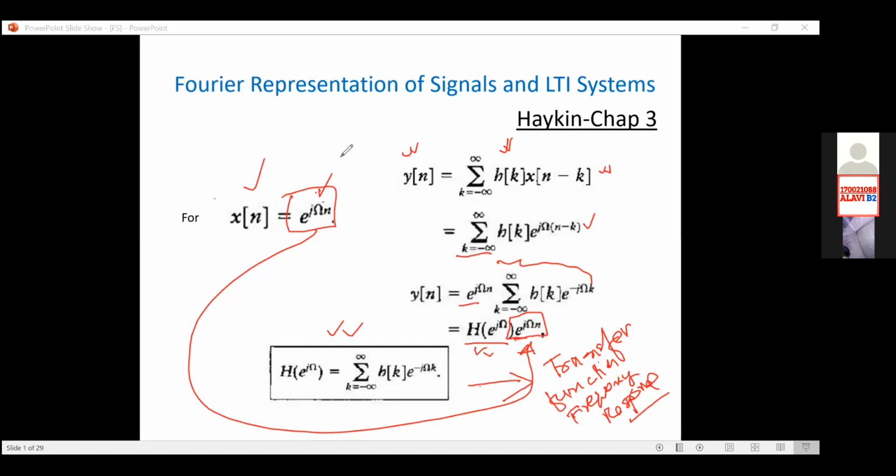Fundamental. So say if we consider that we have a signal with omega 0 fundamental, then the frequencies in your signal are integer multiples of omega 0, isn't it? Yes, sir. Your k cannot be 1.5 or 1.2 or something like this. Your k can be 1, 2, 3, 4, 5. In some cases only the odd values of k will exist, in other cases only the even values, but in general both even and odd values of k will exist.